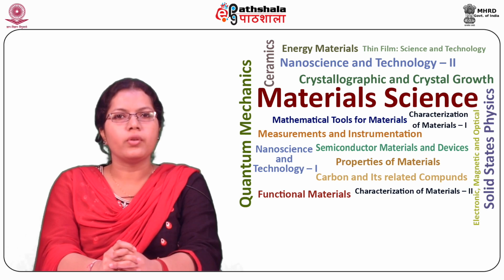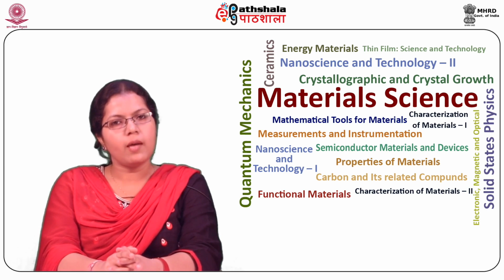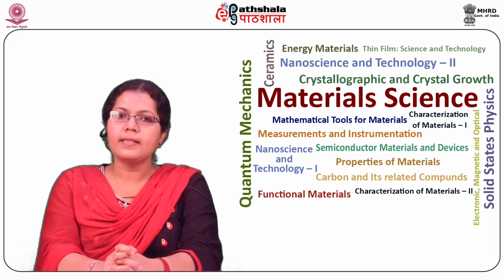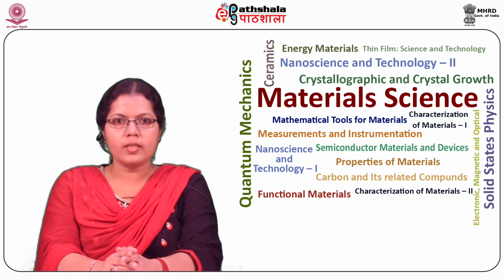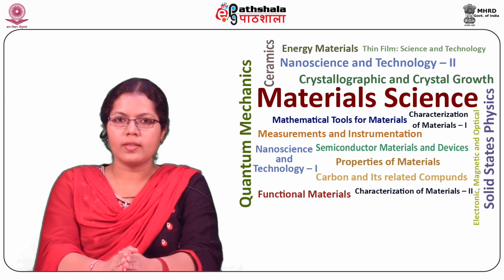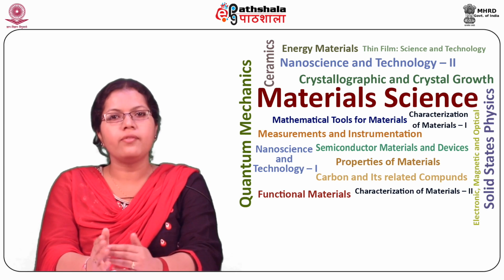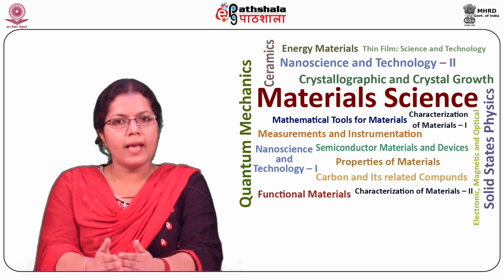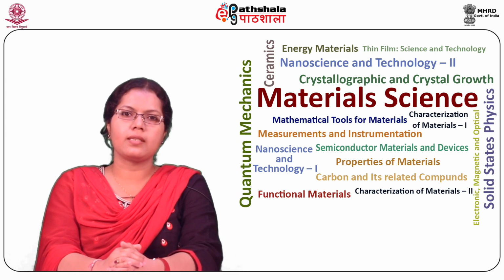Ferromagnetic materials should never be used as eddy current losses in them are appreciable. The use of inductors having ferromagnetic cores is completely ruled out for high frequency applications. The coils should use stranded wires, as otherwise the eddy current losses in conductors become large, especially at higher frequencies. The use of metallic parts should be avoided as the eddy currents induced in them affect the value of inductance.